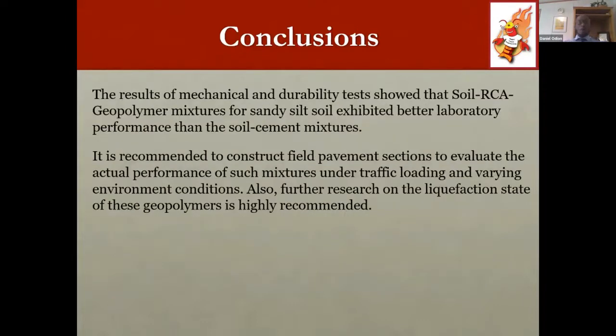So our overall conclusion is that the mechanical and durability test results show that soil RCA geopolymer mixtures for sandy silt soil exhibited better laboratory performance than soil cement mixtures. And we recommend to evaluate the actual performance of such mixtures under traffic loading and varying environmental conditions. Also, further research was recommended to be conducted on the liquefaction state of these geopolymers.